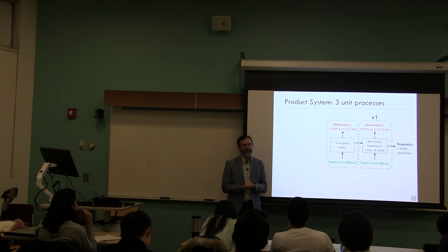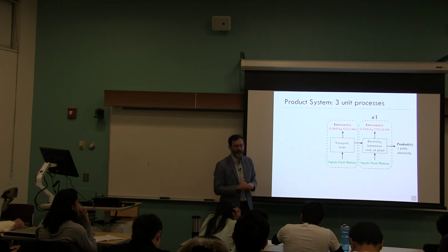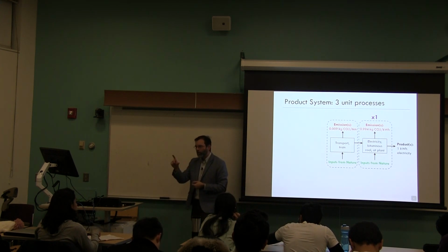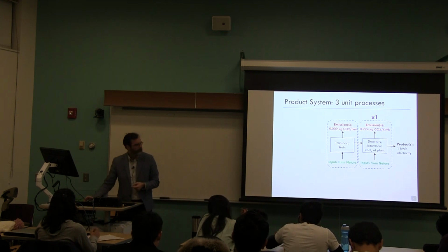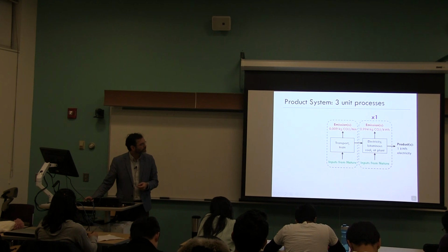Or I can do, again, a mass balance on carbon and diesel fuel, and assuming complete combustion, I can figure out there's about 0.009 kilograms of CO2 coming out per ton kilometer. Right? So you can kind of see that unit here: kilogram CO2 per ton kilometer.